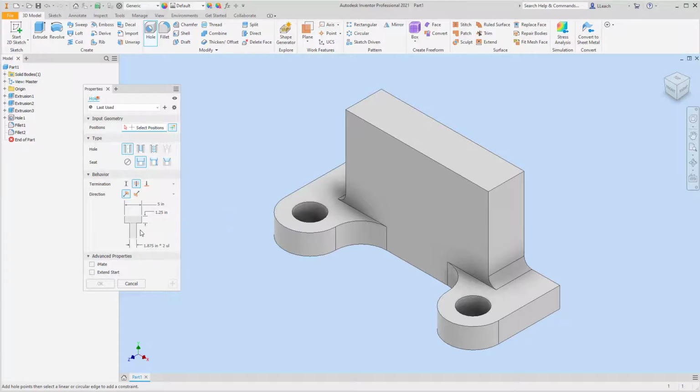And then this hole down here at the bottom, that has a diameter of 1.875 times 2, because they give us the radius. So I just multiplied that by 2 to get the diameter. So just make sure you enter it. Basically what I did was I just typed in 1.875, asterisk, multiply by 2. And then I'm going to click the face of this surface here, just to throw my holes on there.